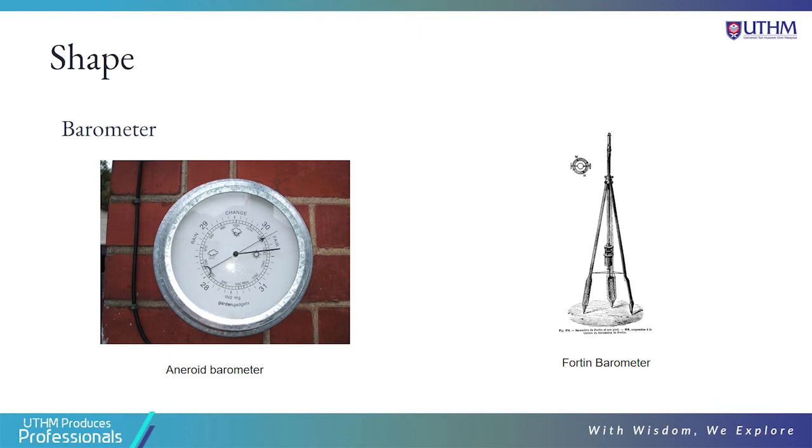Closed-ended barometers can be either U-shaped or well-shaped. In a well-shaped barometer, the tube of mercury stands upside down, or inverted, in a larger well of mercury, so that the closed end with the vacuum is the tallest point and the open end is suspended in the liquid. Outside gases then press down on the well of mercury, which pushes it up into the closed tube.